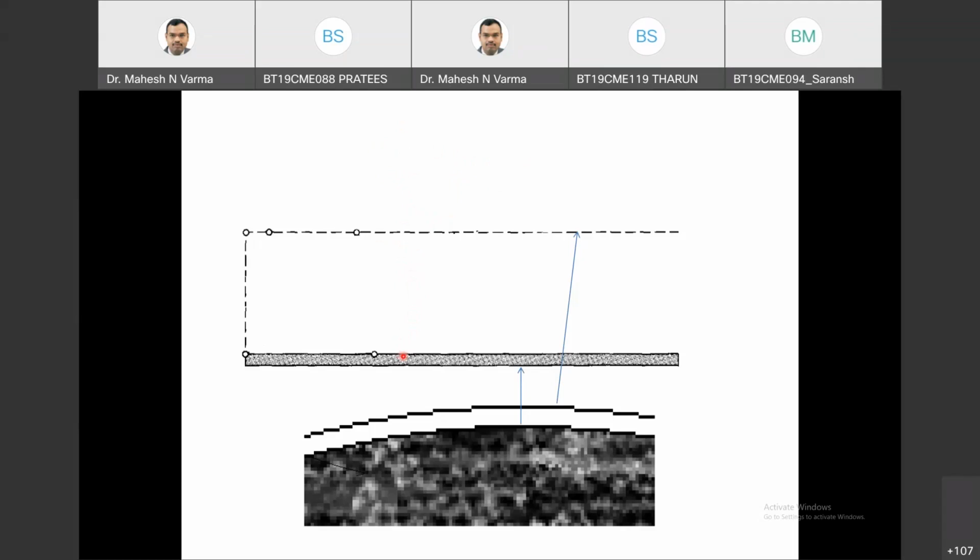B is forming. Here the concentration of B is very small, say 0. Initially it will be 0. At the surface the concentration of B will be larger. Because of this concentration gradient, B will move back. So the flux of A and the flux of B will be in opposite directions. A is moving from the bulk of the fluid to the catalyst surface, and B is moving from the catalyst surface to the bulk of the fluid.